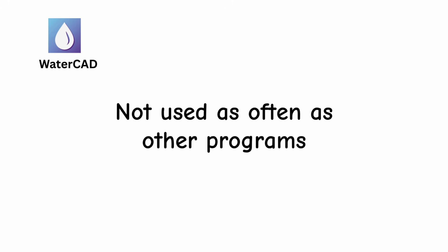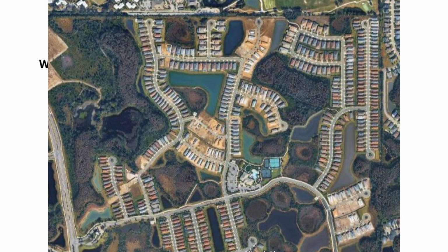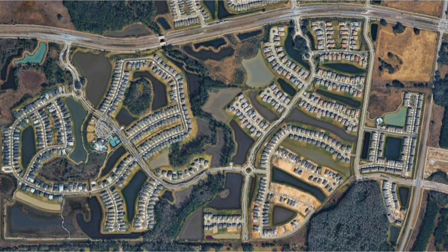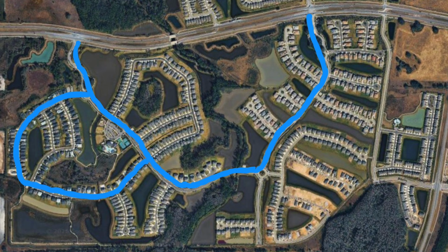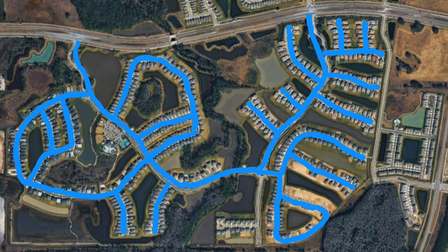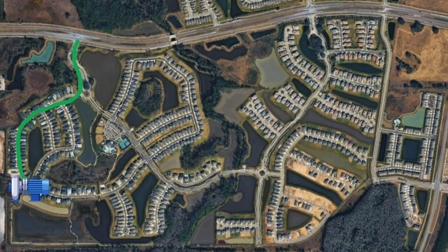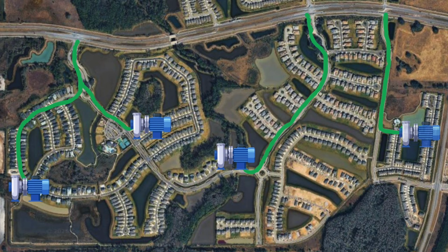I do not use WaterCAD as often in my current work. However, when I was working on more residential projects and master plan communities, I used it almost every week. A large neighborhood may have miles of connected water mains, several connection points, fire hydrants, and hundreds of homes using water. I may also use it for a complicated force main or lift station design, especially when several pipes and pumps interact with each other.